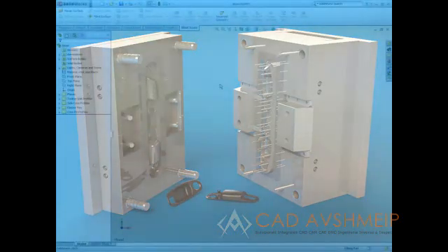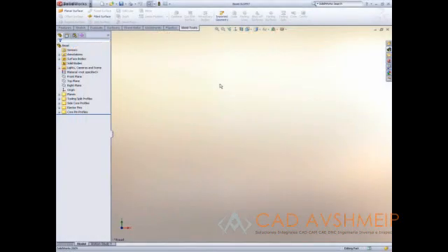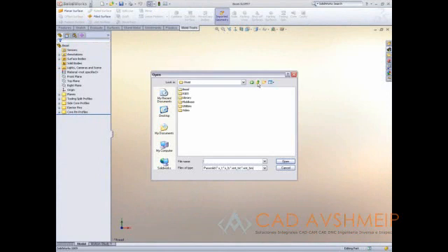Working with different customers requires flexibility when it comes to accepting different file formats. SolidWorks imports a variety of different 3D CAD formats, some of which are neutral formats such as IGES or STEP, and some are native CAD system formats such as ProEngineer or Unigraphics. The file format that toolmakers have been forced to work with over the years is IGES, and geometry errors are commonplace.